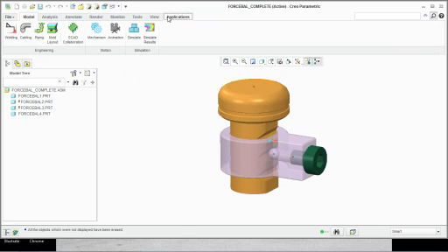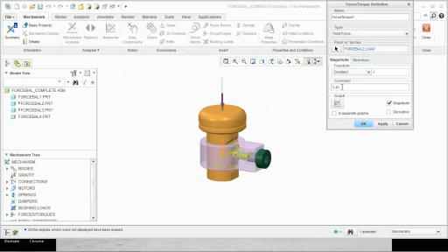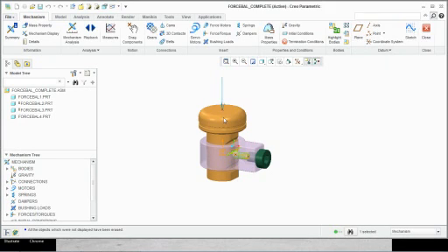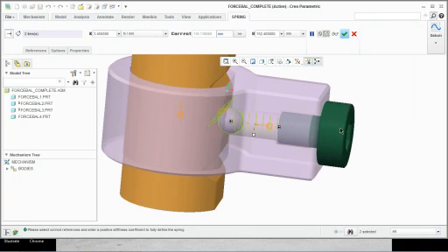You see there is the force acting on this little part, right? It's at 3.45, so something's pushing it down. Notice that there is a spring right here. The spring that's pushing this ball is connected to this particular nut. Notice the K value of the spring. Notice the current position is 116, but the unstretched length is 152. That means the spring is compressed and it's pushing it that side.